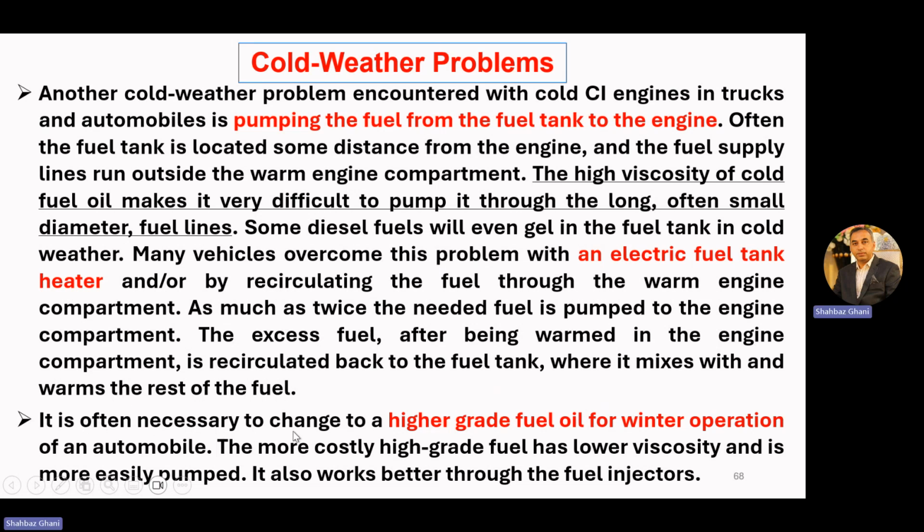It is often necessary to change to a higher grade fuel oil for winter operation. So in winter, we need to change the fuel and oil with respect to the temperature changes. More costly higher grade fuel has lower viscosity and is more easily pumped. The higher grade fuel is costly. It has a lower viscosity, so it is easy to pump. It also works better through the fuel injectors.